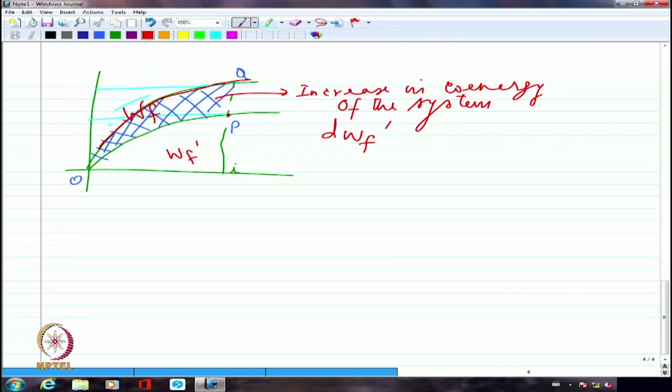If we are doing it slowly, automatically the current will remain a constant, RMS value. Current is not really controlled by you completely unless you are varying some resistance. We are saying right now that the resistance is a constant. The inductance is changing. Clearly, for every change in inductance there will be a transient, no doubt. But we are doing it so slowly that the transients are not so visible, because the time constant happens to be really small compared to the rate of movement.